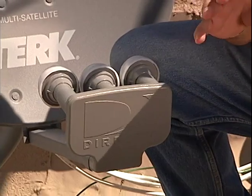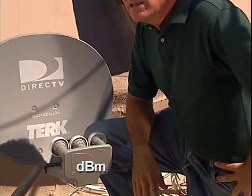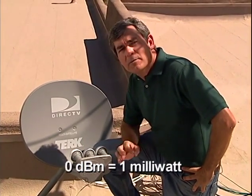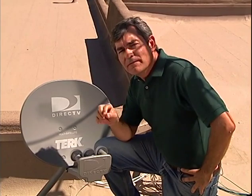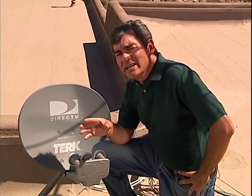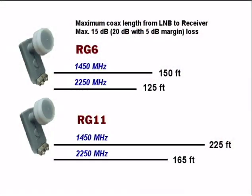Now, the signal level out of a LNB is expressed in dBm. Similar to dBmV, only it's a unit of power rather than voltage. 0 dBm is a reference of 1 milliwatt. Now, typical signal levels out of an LNB are minus 35 dBm. That's sort of equivalent to plus 3 dBmV in a 75 ohm system. Therefore, the loss from the LNB to the receiver can't exceed 20 dB.